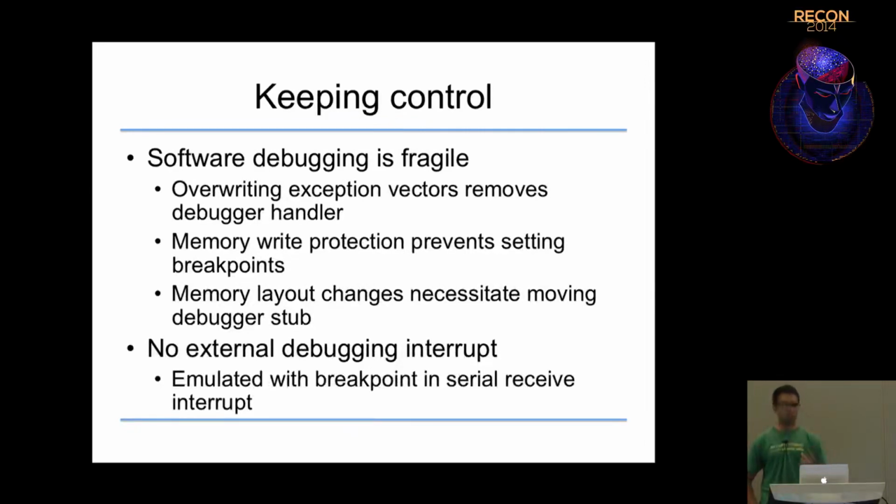And there's also no external debugging input. But for this, I found a quite nice trick. I just put a breakpoint in the serial port interrupt so that I could just send a character to the drive and have my debugger back.